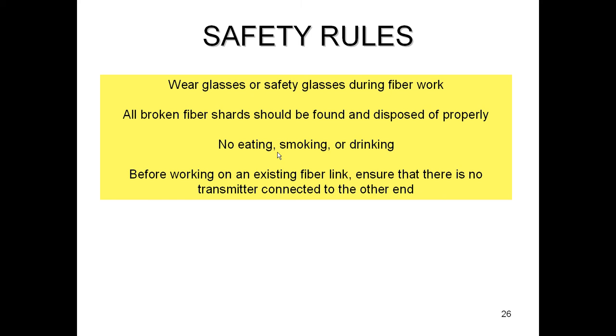You know, I've had them stuck in my hands. I've had them stuck in my elbows. They don't really hurt that much. You just pull them out. But if you get one in your eye or you swallow one, that's bad news. So you always wear safety glasses when you're working with fiber. You make sure that all your broken fiber shards are properly disposed of. They make special cans, plastic cans, to put the little pieces in.